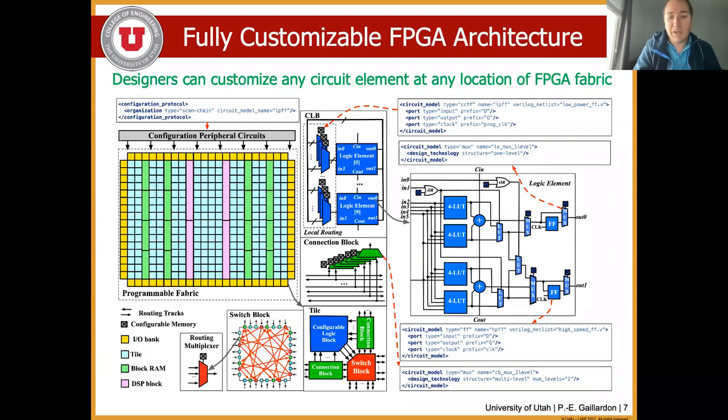And if you look at the FPGA, well, actually, where we are is a good example. So think about a very large fabric. In a very large fabric, you have plenty of LUTs. In every single 4-input LUT, you have a bunch of SRAMs plus routing multiplexers. That's a lot of logic cells and memory elements, a lot of transistors, basically. And now you will want to formally verify that a 2-input AND gate that you are mapping onto this fabric is formally equivalent to this very large fabric programmed to be a 2-input AND gate.